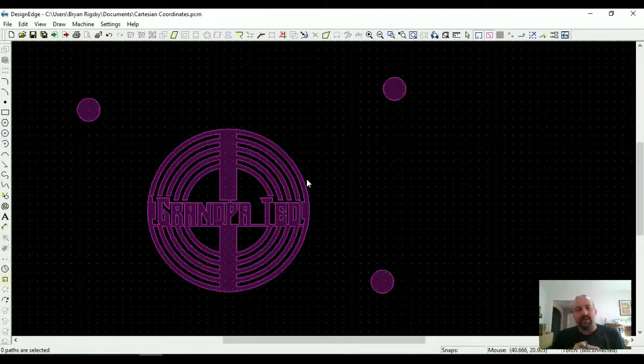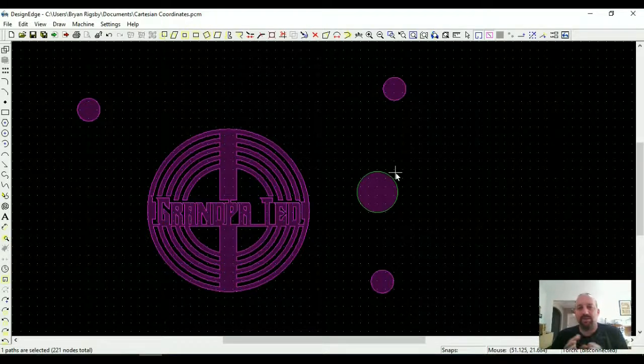One brief bit I want to say about entering those formulas when you do a mixed number. So if I wanted a Q circle from here, and I wanted that circle to be, let's say, 4 13/16 diameter. So that would be 4, the whole number, and then plus the fraction, 13/16. So for a circle 4 13/16, you just enter the plus in between. So no space, just use 4 plus. For 1 3/8, it'd be 1 plus 3/8.